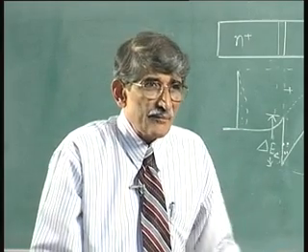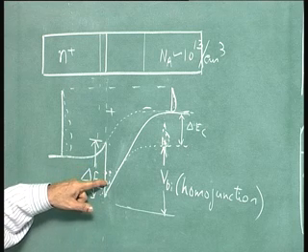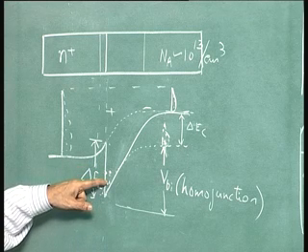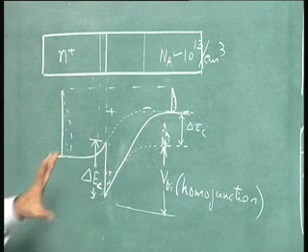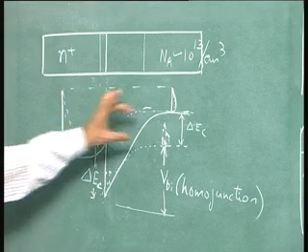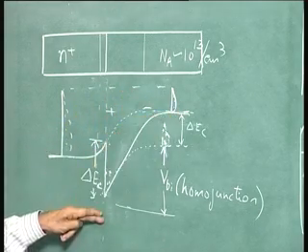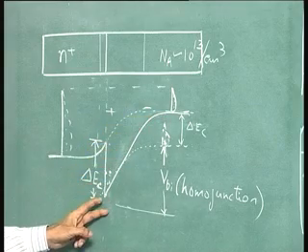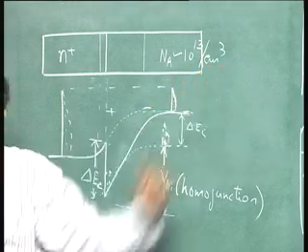I just put this diagram to tell you that the extent of electron concentration here depends upon thermal equilibrium condition: the more this notch, if delta Ec is more, that is more, because it will come from here, go up like that. The more the potential change in the semiconductor, the more will be the charge, that is, the band bending is more.